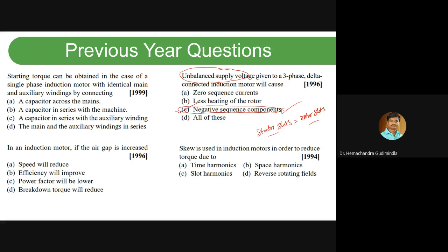That phenomenon is called cogging. So what we will do is rotate the rotor by a small angle. If you rotate that, what will happen? We will reduce the vibration and noise, and we will also maintain the air gap, because if both are strongly aligned, then it won't rotate, it will vibrate. That is because of slots, or we can say slot harmonics.